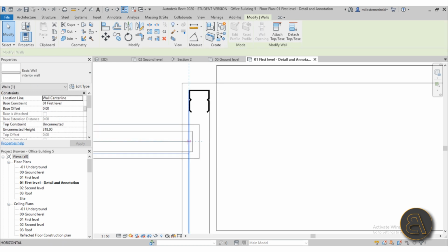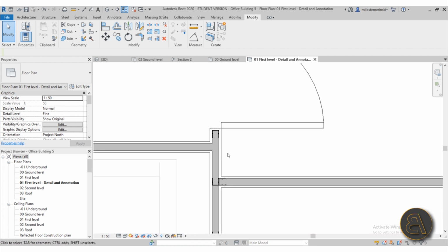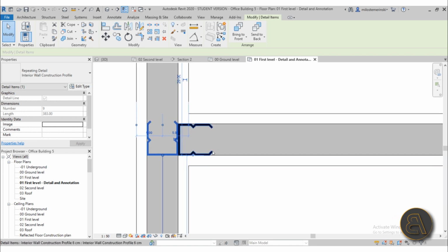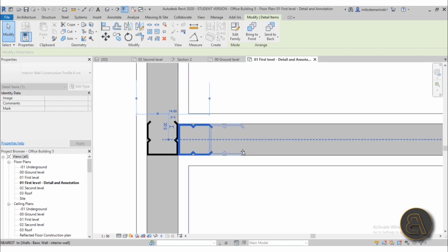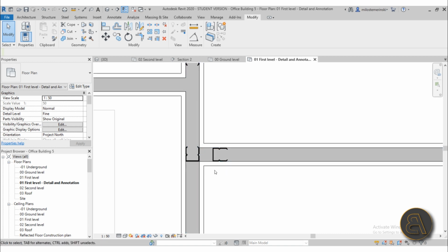Now, if we try to disconnect this or attach it there, it's going to automatically connect, so that isn't really an option. So what you can do in that case to fix that up is, let's go ahead over here and maybe make a change. Let's move this out a little bit. And let's start playing around with this wall join. To change the wall join, you need to go here to your modify tab and go to your geometry panel, and here we have the wall join tool.